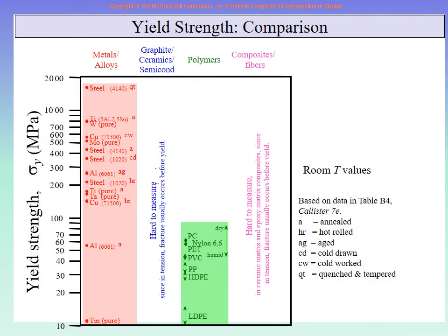Right? So you understand the reason. Ceramics are very brittle. Brittle means that only the straight line linear elastic region is there, though it may go to very high strength, but suddenly it just breaks. Because it does not start plastic deformation in a very significant manner, therefore there is no yield strength.